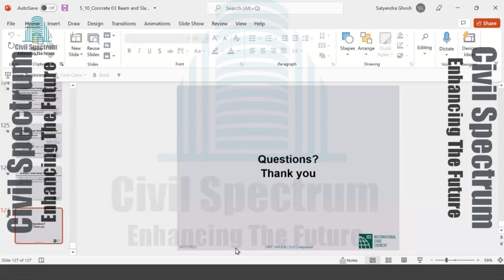You take a column in design category D, which will be the newer parts of Dhaka. You go to Uttara or wherever near the airport. So design category D column, the confinement requirements are so high that the hoops that you will provide at tight spacing, those will be way more than what is needed for shear, way more. Yeah, this is common. This is all the time.